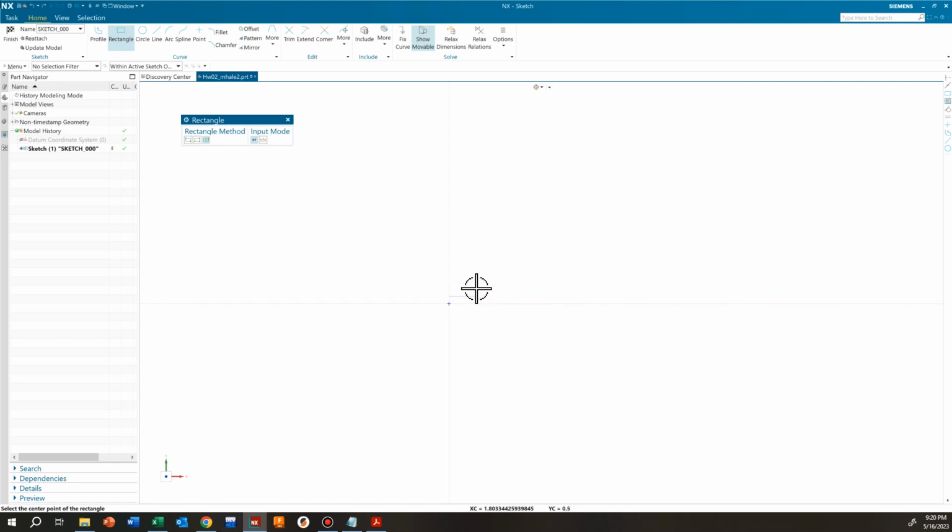But what we're going to use for this one is if I just hover over a spot. You see how those three dots popped up? So let me do that again. I want to click on this origin, but see how I can't really get to it for certain. If I hover over that spot, I'll leave it there for a second. Those 3 dots appear. Now if I click with my left mouse, this window appears and I get to select exactly what I want. So see, I've got a point on a curve. I've got a point on another curve. That's this axis and this axis. I also have the existing point, which is our sketch origin. That's the one I want to select. So I will click on that.